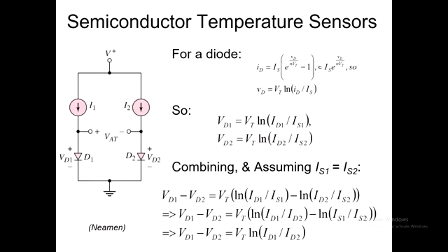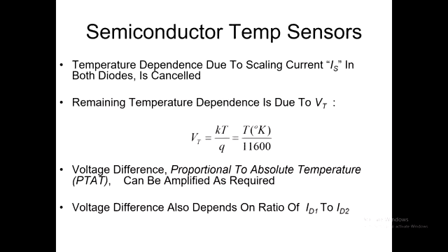Yep. If that's the case and we get the thing to operate, then we can measure with a differential amplifier, instrumentation amplifier if you will, between those two points, and we can calibrate that for temperature.